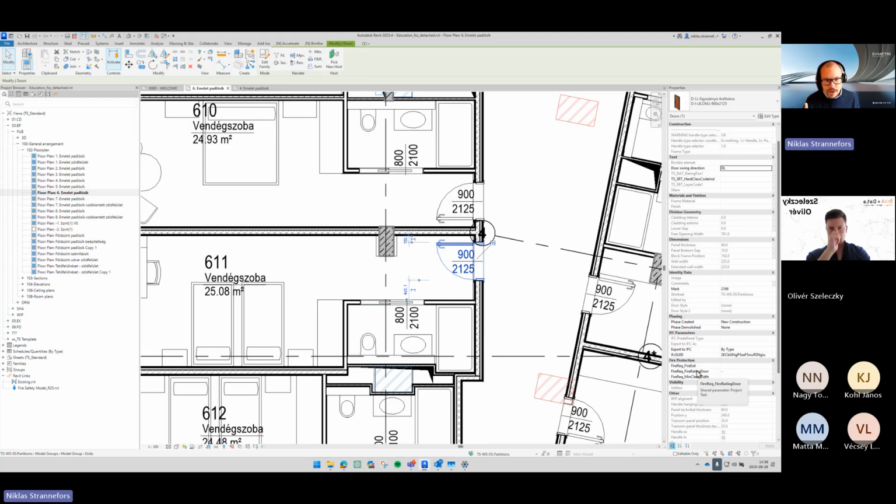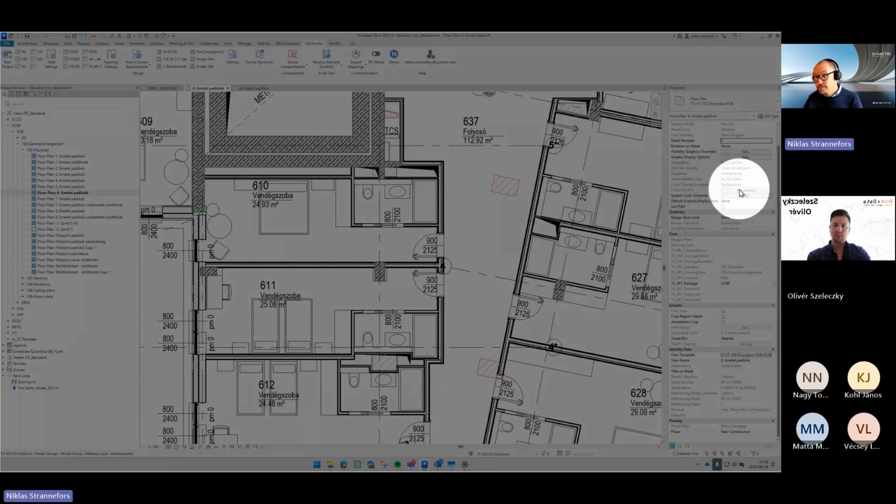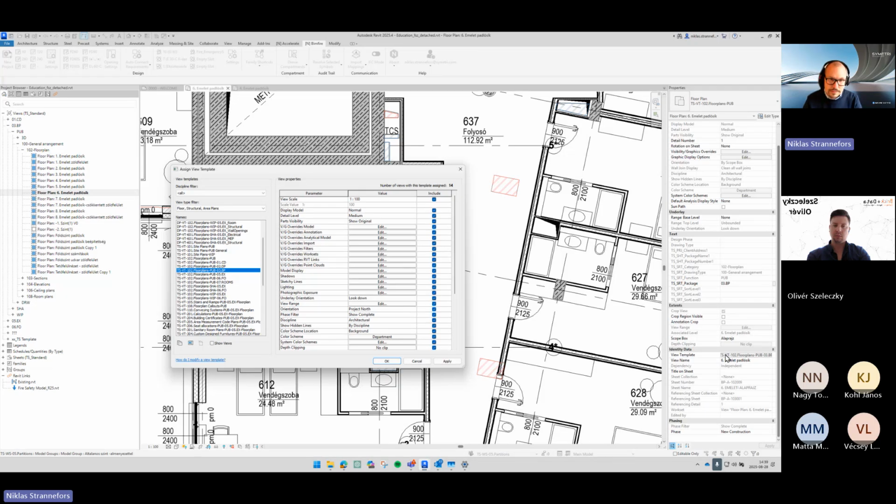One thing I want to show, the last one, I almost forgot. The room requirement, where I wrote exit staircase, fire lobby, escape corridors, etc. We didn't send that information to the architect model because we only sent two parameters, doors and walls. But the good thing about spaces and rooms is that they have a color scheme called department. They're looking at rooms and applying a coloring on departments. If I go down here to view templates, their view templates, which is called TS VT 100 to floor plans, something, we can open their view templates, still pretending to be architects.